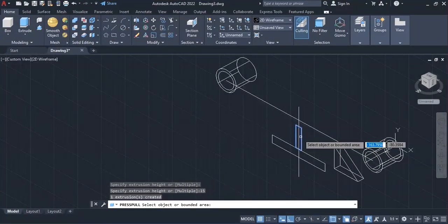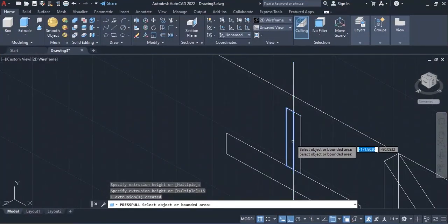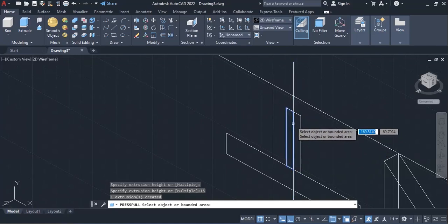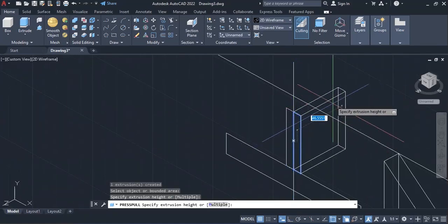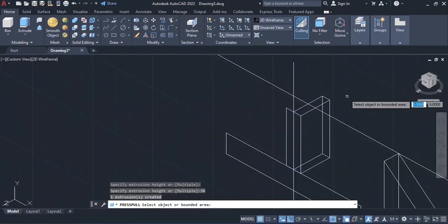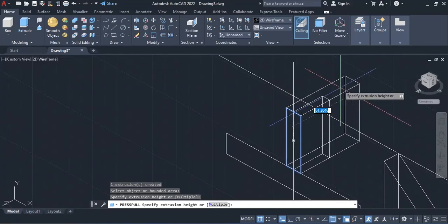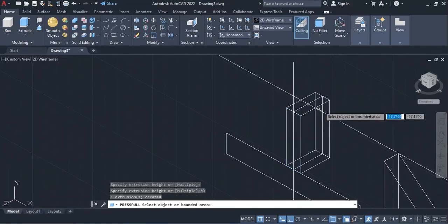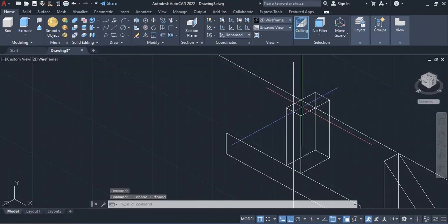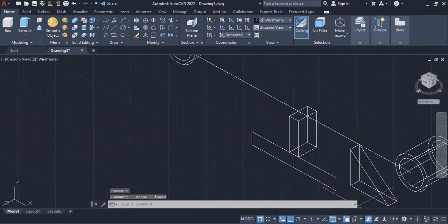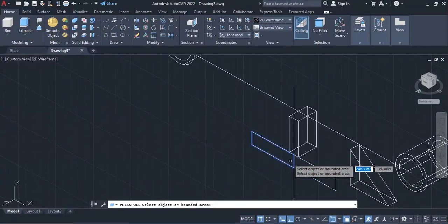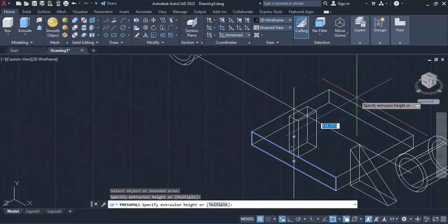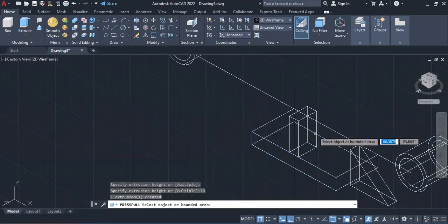So this bit, we'll do it twice. So the first one 30, the next one, okay, because it's accepted for 30. Then I can delete this one. Then the bottom bit will press pull it by 70. So we come to press pull again. So that way, then 70, then enter.